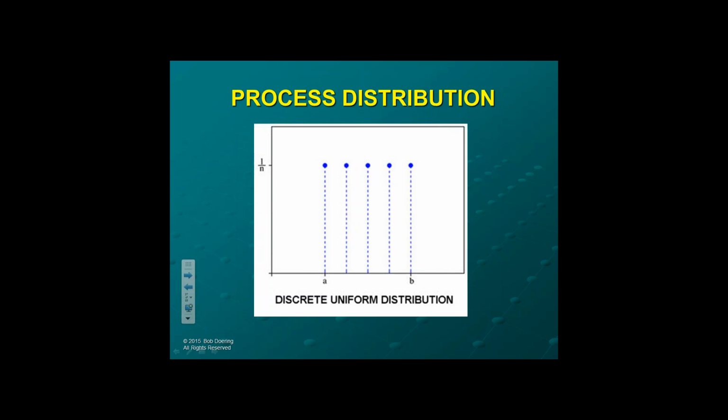That's good data. Then they discovered that over time, if you get to a point, you're going to have to make an adjustment or else it's going to get too large. Now they came up with some pretty unusual calculations to determine when to make the adjustment that weren't exactly right. But one of the things they did identify for sure is that you have a sawtooth curve with machine variation from tool wear. And that's important.